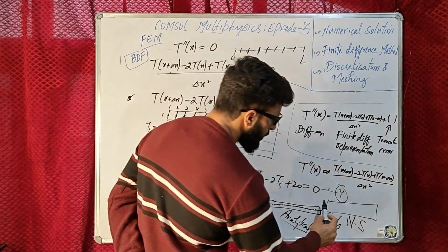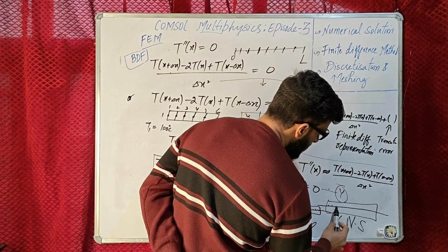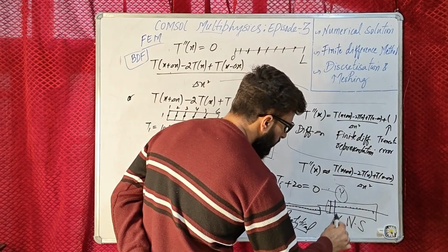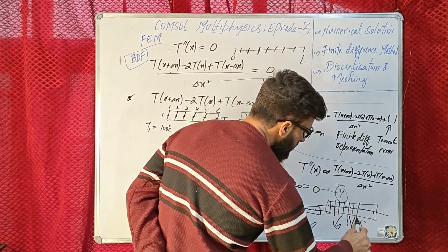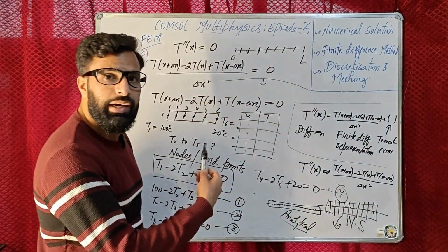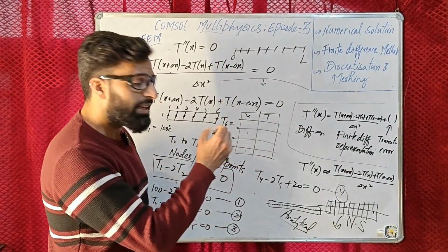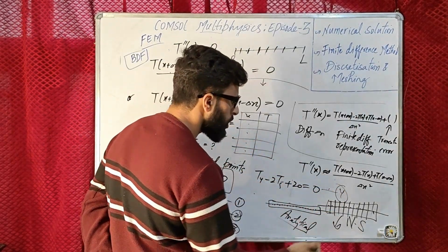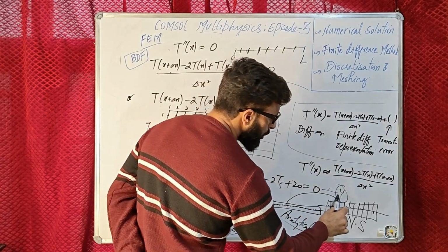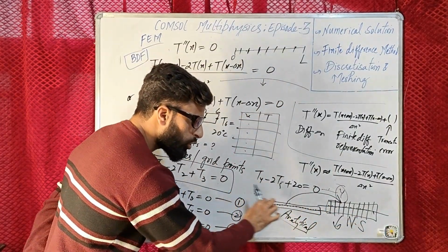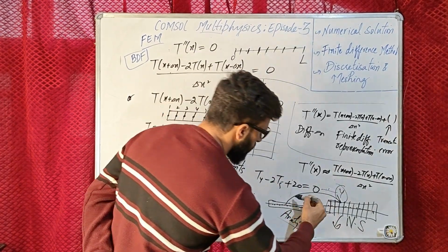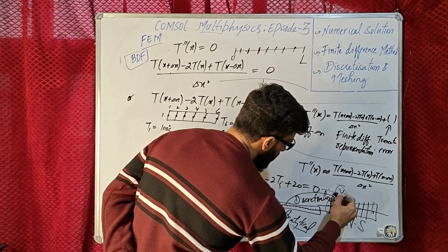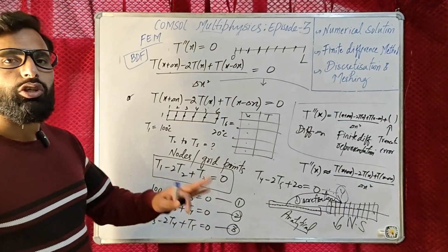Numerical solution is not available continuously at any point in the domain. It is available for selected points in the domain depending on how we divide the domain. It's available at discontinuous points, at selected points, in other words at discrete points. So this is known as dividing the domain into discrete points, dividing the entire domain solution into discrete points. This process is called discretization. Now discretization is of two types.